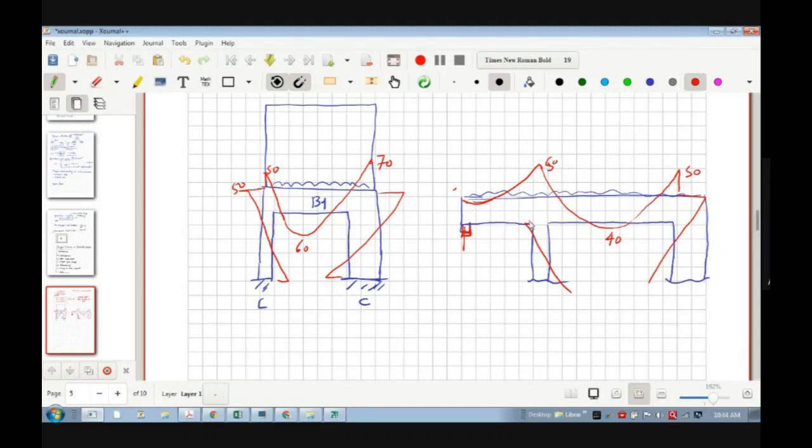See, because of this beam, this moment got reduced actually, and it got distributed in this beam. So there is a uniform distribution of bending moments. So this is very important, uniform distribution of bending moments, because now this person is sharing with this. Previously, B1 was only the person who was sharing the bending moments. And due to that, even this column was getting more moment, let's say 50 here. And now it is, let's say 5 kilonewton only, because now the column is having less moment because the bending moment got shared in this beam B3. This is my B3 and this is my B2. Okay. So it got shared here. So I got a uniform distribution of forces.